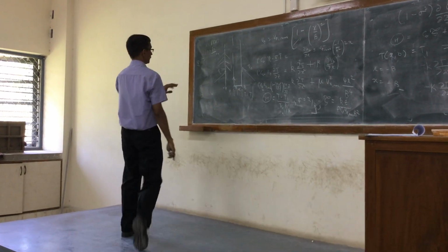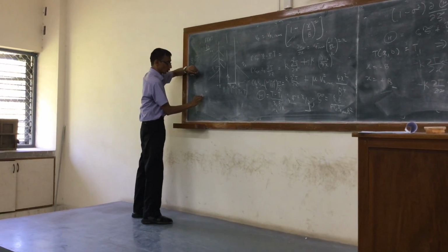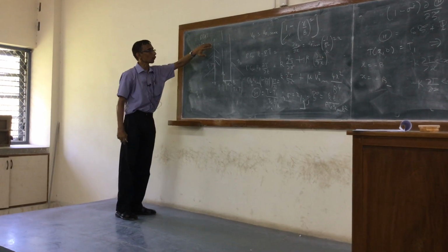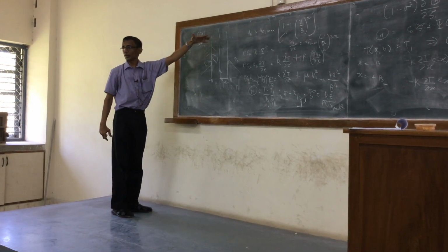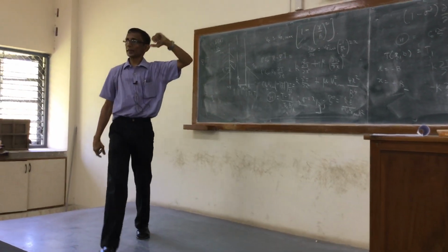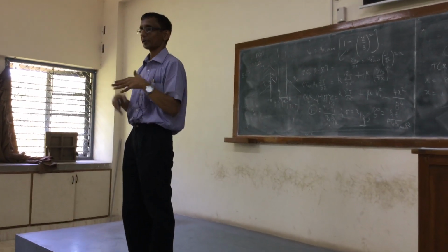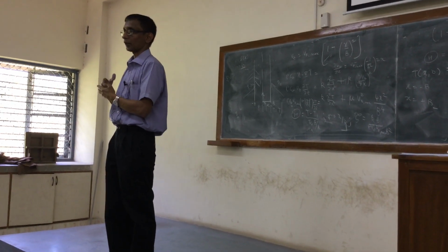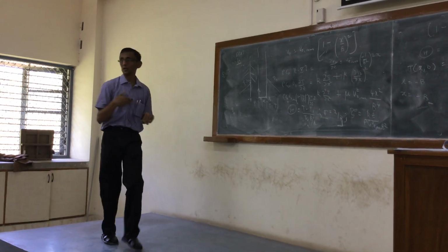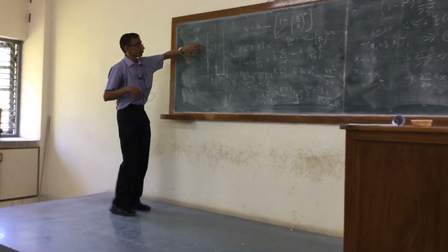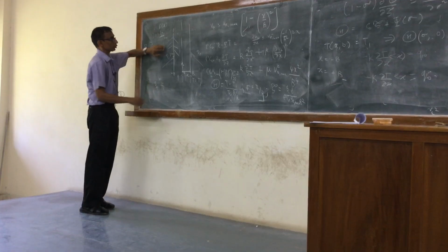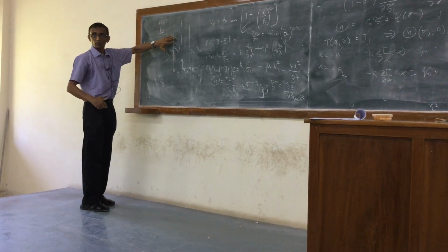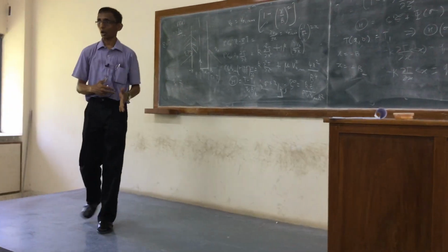At x equal to minus b, what is entering is clearly Q naught. There's no doubt about that. That is now equal to what must be leaving the surface into the fluid. That's taking place by convection, so that is where the k dT by dx will come in. And here it's very important to remember the sign convention. So this is what I am going to equate it to: the flux that is being transmitted to the fluid from the wall.